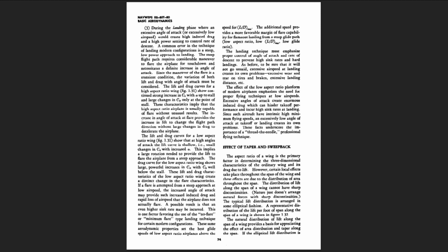The effect of the low aspect ratio planform of modern airplanes emphasizes the need for proper flying techniques at low airspeeds. Excessive angles of attack create enormous induced drag which can hinder takeoff performance and incur high sink rates at landing. Since such aircraft have intrinsic high minimum flying speeds, an excessively low angle of attack at takeoff or landing creates its own problems. These facts underscore the importance of a thread-the-needle, professional flying technique.